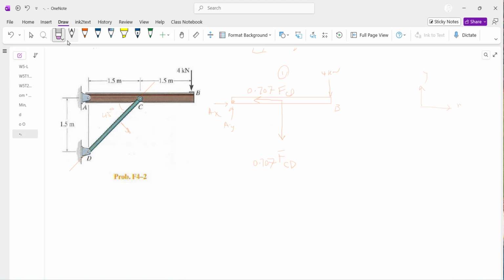So this free body diagram is similar to the previous one, but the difference is now all forces are in X and Y coordinates. So let's try the condition of rotation about A. The conditions: net forces in X equal to 0, condition 1; net forces in Y equal to 0; and net rotation, I would take with respect to point A. Why point A?